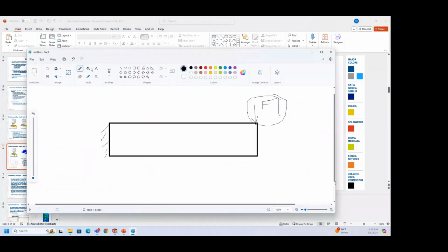Just quickly, coming to the governing equation, I have m into x double dot, which is my acceleration, plus c, my damping factor, into velocity, plus stiffness into my displacement, equal to f of t. When it comes to linear static analysis, the inertia part and the damping part, or the acceleration and velocity, are neglected and zero.